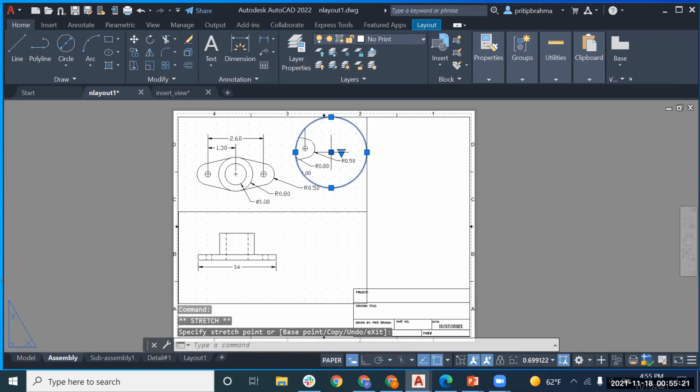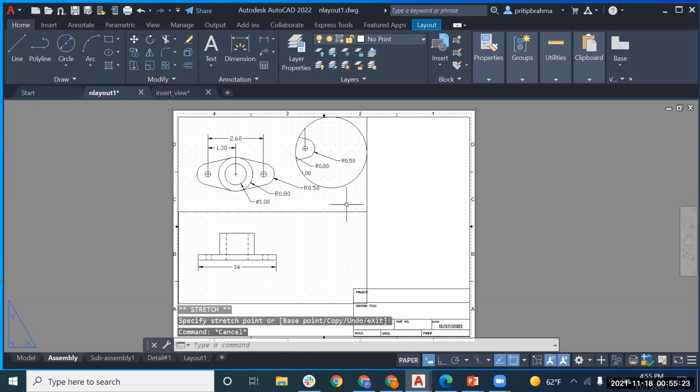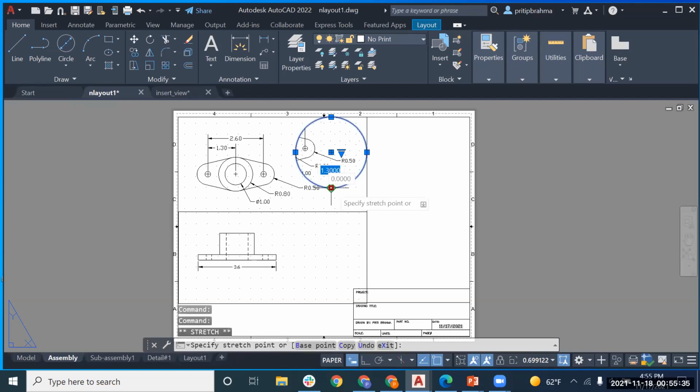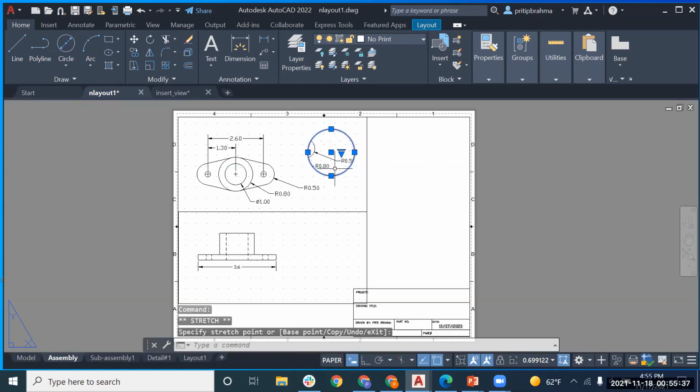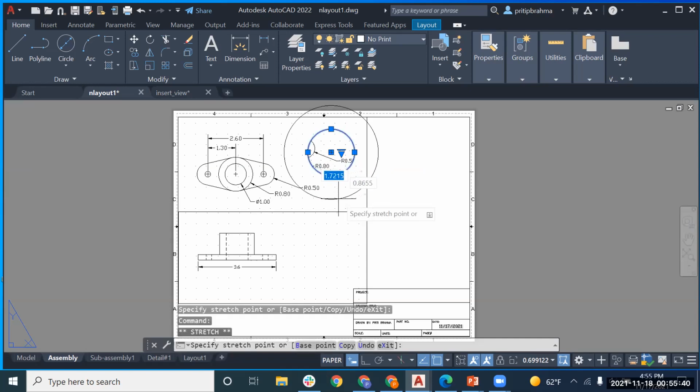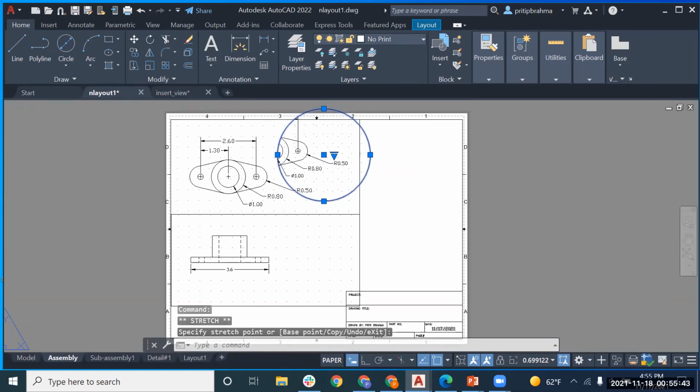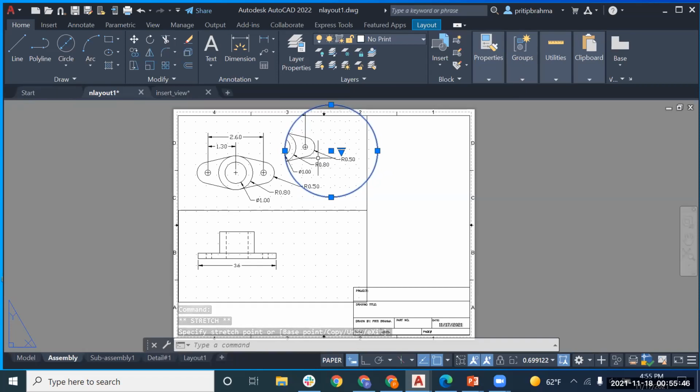And I can move this viewport over here on top of another viewport, and I could draw an arrow as well that shows the enlargement. So that's how you could actually call it out. You can also make it bigger or smaller, so if it's too big, make it like that. And then zoom in to the area you want to show and just draw a leader line up to this arrow, up to this viewport. So that may work for some of you, some of you may find that very useful to get into those smaller dimensions.